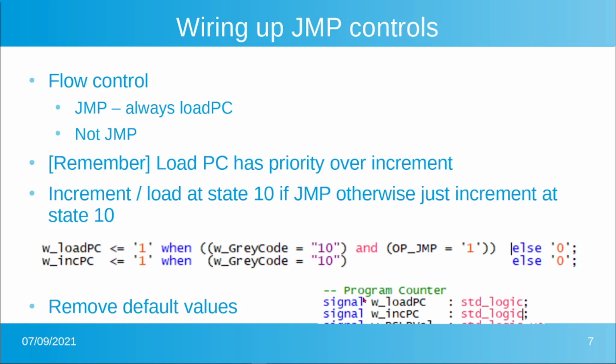We do want to remove the default values that we had set for those. They had equals something out here. I think we'd set them to 1 or something else, but basically now we're driving them. So it's single clock wide. It's combinatorial here. It could be set up to be less combinatorial. It could be set up to be registered if we wanted a little more timing flexibility.